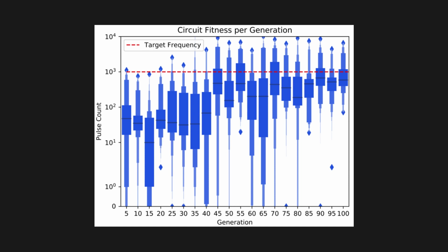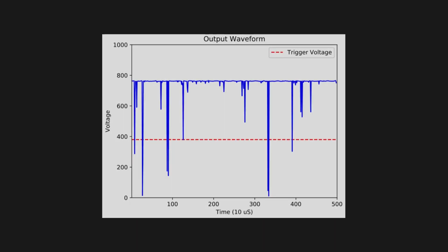Firstly, fitness assignments for this function are nonlinearly related to the signal measured. For example, a circuit that generates 997 pulses has a fitness of 0.33, where a circuit that generates 998 pulses has a fitness of 0.5. Linearizing fitness assignment could massage the population's mean fitness to something more stable. Secondly, the unsteadiness of mean fitness growth may be a result of using rising edge interrupt handlers to count pulses, an evaluation mechanism which may be too coarse for the creation of stable analog oscillators, a sentiment echoed in Thomson's work. Let's go ahead and take a look at the output signal.